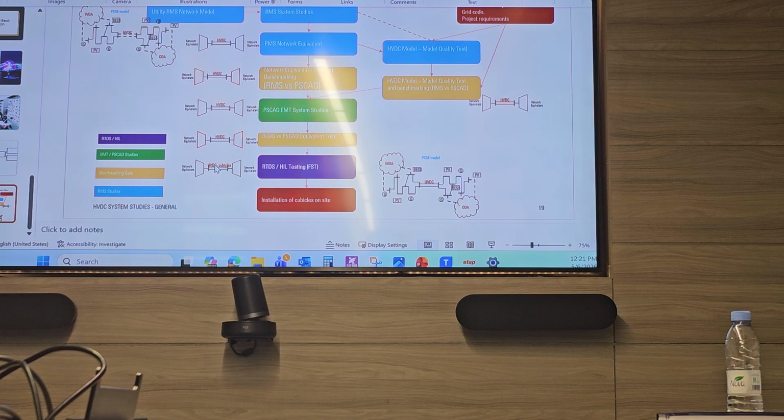And why are you doing these studies? You want to check if your pre-selected equipment is suitable, you want to check with load flow, short circuit, protection coordination. During project execution, you want to make sure that you are not making any mistake, which could be very costly if you discover something in a late stage of the project.